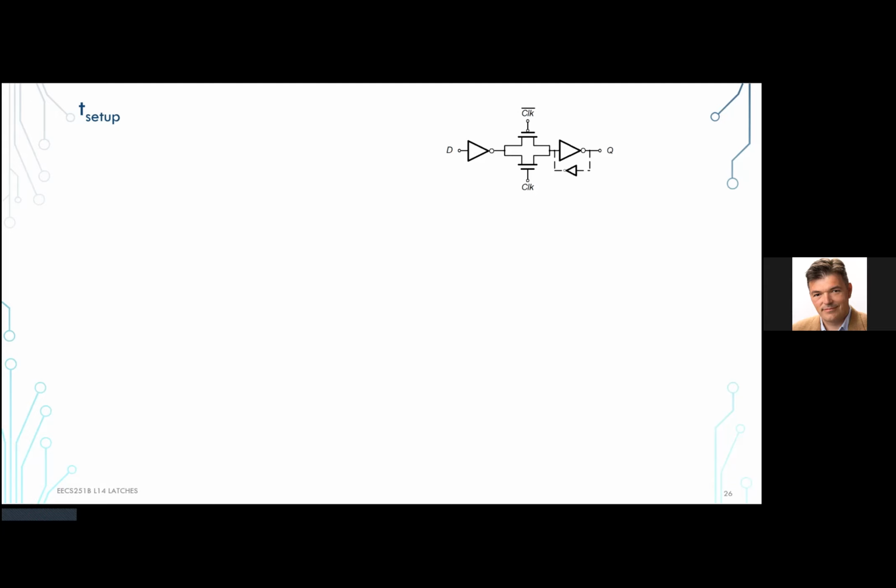Well, if you look at that, that delay is roughly split in half. You can do the actual calculation, which is telling me that the propagation of this inverter should become 1.1, 10% longer, or a little bit more than 10% longer. How does that happen? Well, if this input does not reach the rail, does not reach all the way to ground.